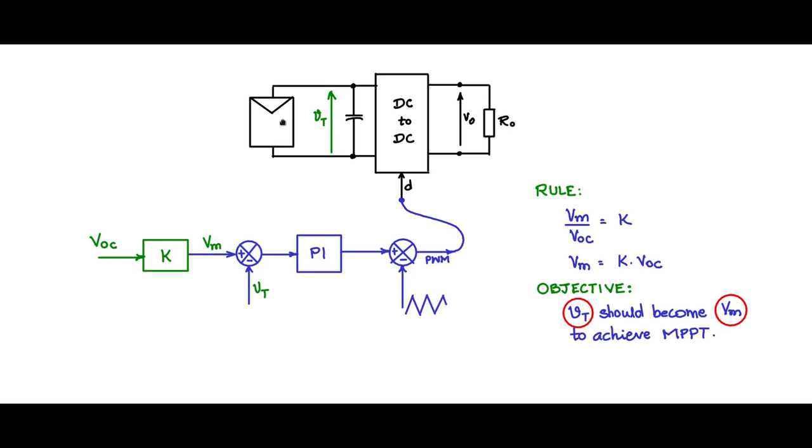In the neighborhood of this panel, which is delivering power to the load, we will place a small cell called the reference cell, and that reference cell is kept open circuited. There is no load connected across the reference cell. So this cell, which is placed in the neighborhood of the PV panel, wherever this is placed on the rooftop, you place this reference cell also. This is a small cell.